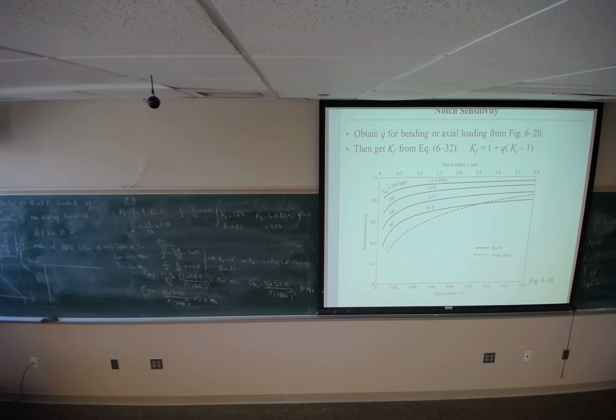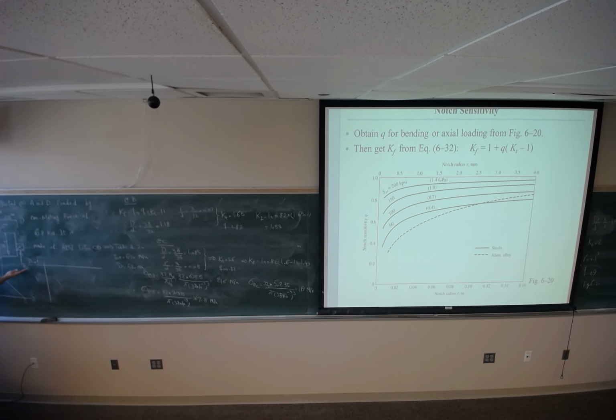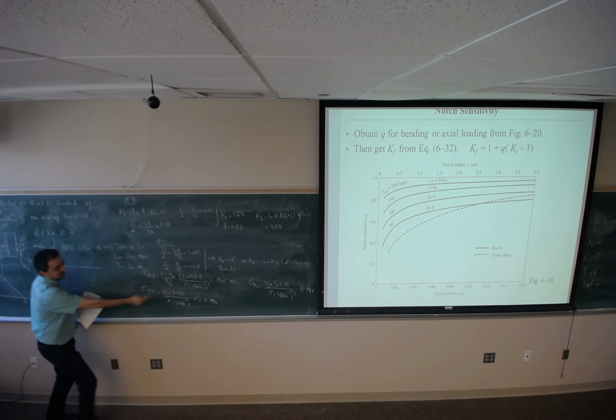Now I make this table of points. I'm going to have all three candidates for critical section here, just to show you what the process should be. But we know that point E is out of the picture, so we don't look at point E because there is no fatigue concentration factor, and it has a smaller number than these two.